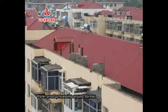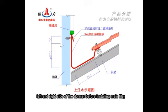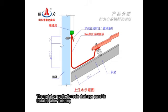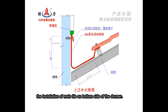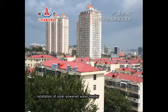Waterproof processing around dormer. The metal or synthetic resin drainage panel should be fixed on top, left and right side of the dormer before installing main tile. The metal or synthetic resin drainage panel is installed after finishing the installation of main tile on the bottom side of the dormer. Installation of solar-powered water heater.